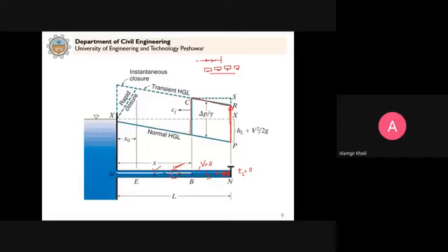So when this pressure wave reaches here, it will bring this pressure to this value. When this reaches here, it will bring this normal hydraulic grade line to this. And the pressure is delta P by gamma. This is the increase in pressure due to this water hammer. When this wave reaches each point, it will bring the pressure from the normal pressure to this maximum value.